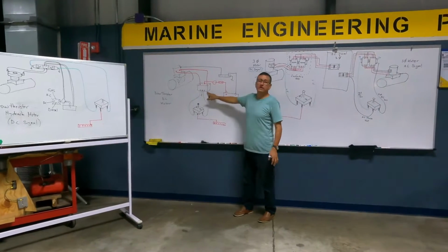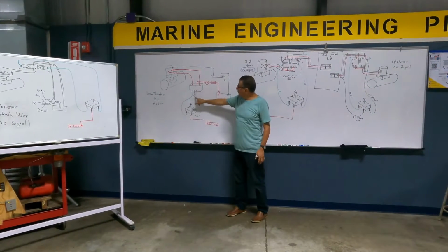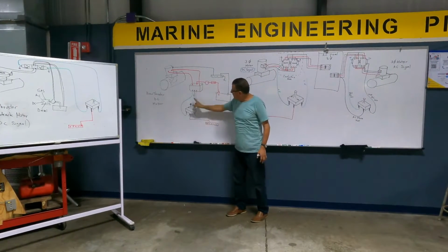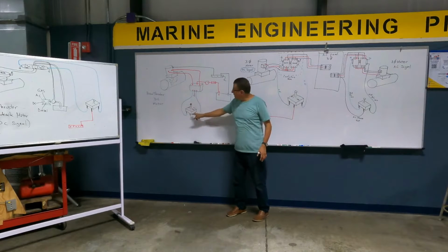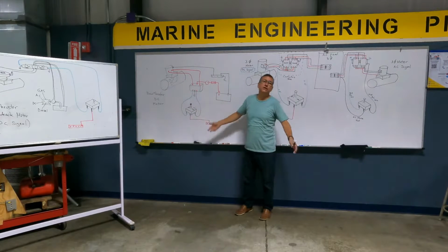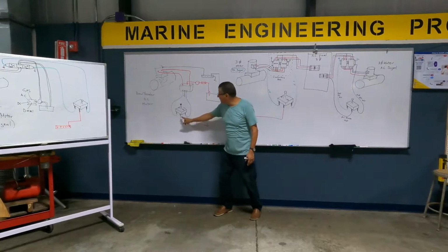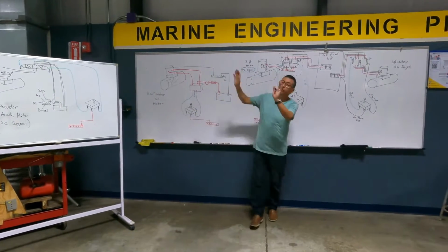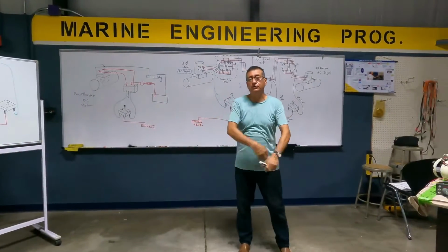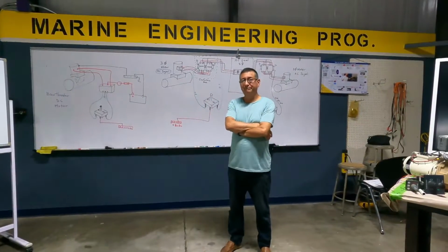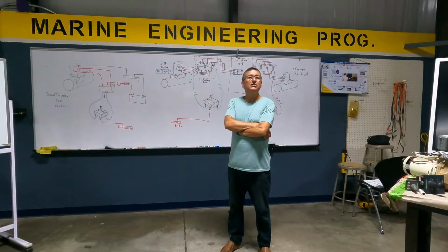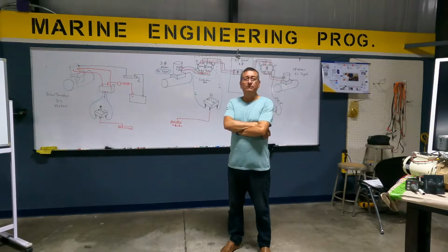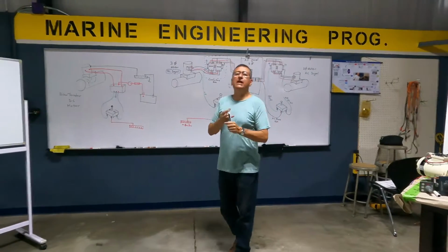And here 3 terminals. The middle for ground, signal, and signal. And those are coming from the joystick. The joystick receives power in the middle and sends for one side and sends for the other side. And bingo, finito. This is the installation of the bow thruster. It's not complicated. It's simple.